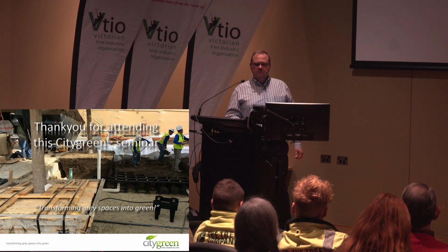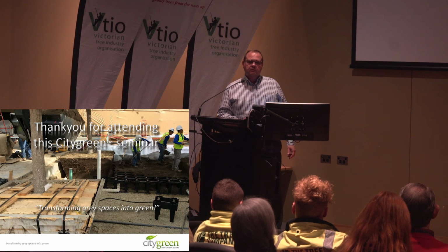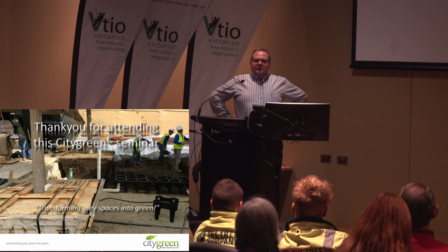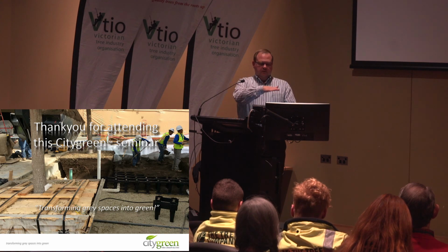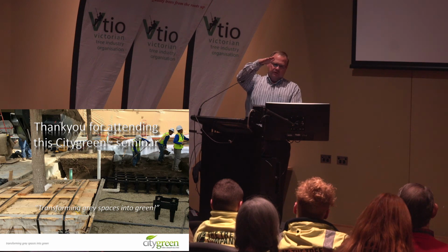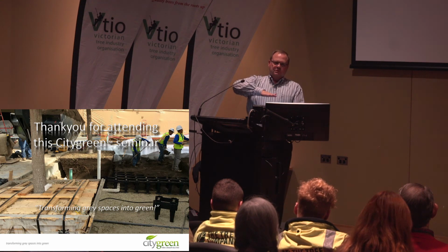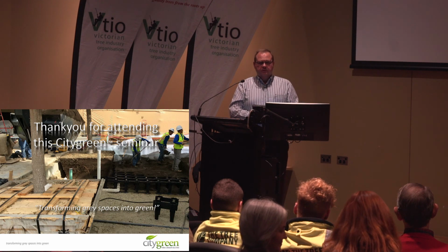Are you testing, say, the oldest sites you've used? Sorry, what was that? Are you testing the oldest? It's hard to test because they're buried. We have done destructive cyclic tests. We had to do that for the City of Auckland when we did the waterfront over there. It was actually done at a university lab, placing one of these vault systems under cyclic load 10,000 times and then crushing it to see if the ultimate load strength was compromised, and it wasn't.